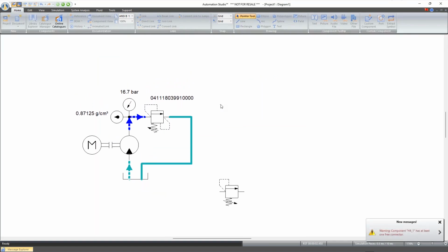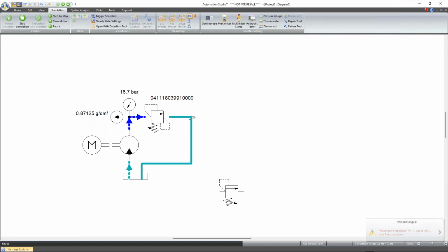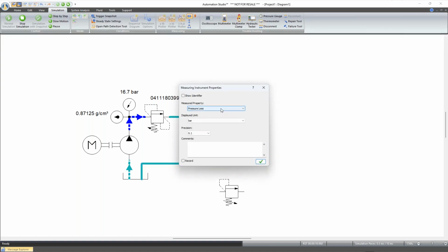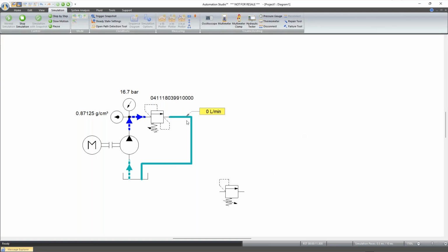And then when I simulate, well, here the result is very obvious. I've got no flow coming out of the relief valve because I think I put quite a high leakage coefficient. So now I think I'm losing all of my oil out. Maybe if I decrease the pressure based on the coefficient, I'm still allowing some oil, but if I do, my flows balance, no, I'm still losing quite a bit of oil because of this external failure.